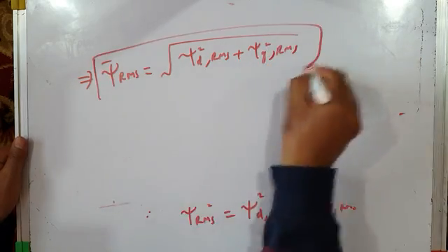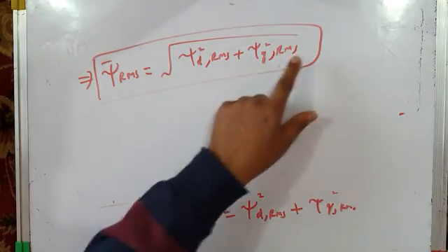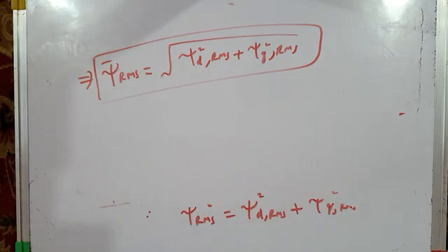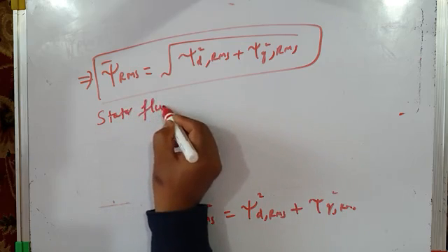That's it. Now you have already developed the equations. You have the equation for psi D RMS. And what was that equation for psi D RMS? We found it earlier, just a moment back. It is 1 by 3 d square t1 plus t2 by ts whole square, and the square root of that. And psi Q RMS, just a few moments back we have found. Take the square of that, take the square root of psi D square RMS plus psi Q square RMS, and that will give you the total stator flux ripple. So this gives the stator flux ripple.